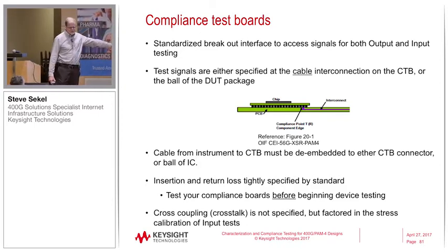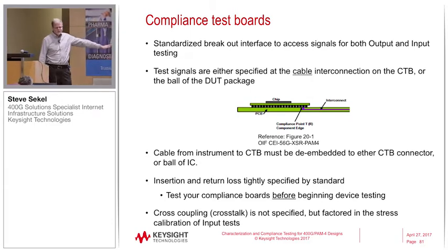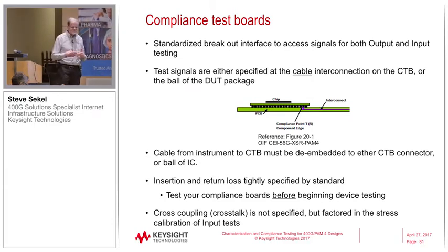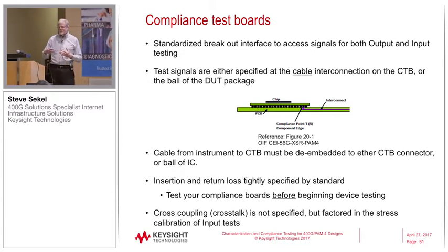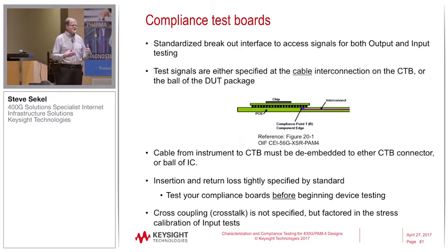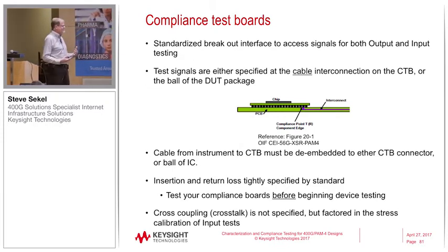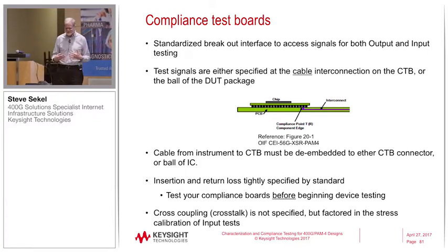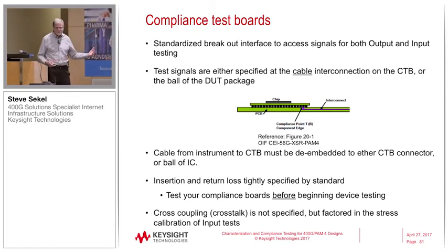For the ones that you can purchase, which are basically the pluggable optics boards, you would think they are all fine, but Rob mentioned that various companies have different performance levels, and we won't mention names. Even if they come with data, that does not necessarily mean the de-embedding was properly done when they were characterized. So it's worth your while to take a few hours in the lab and validate the boards before you do a lot of work with them.